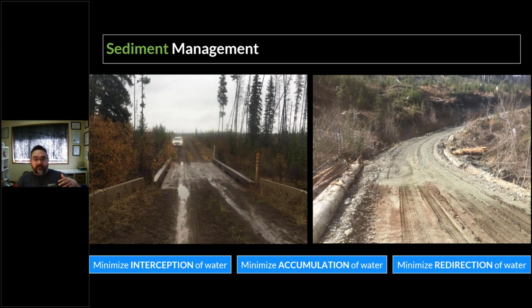So now you have to think about bridge lengths, or what type of crossing. In the resource sector, we're notorious for having our crossings in a swale on secondary or temporary roads, because we're trying to do it on the cheap. The streams are in big draws or gullies, so we're swinging in and out of them, and we can't afford to put a big bridge across that.